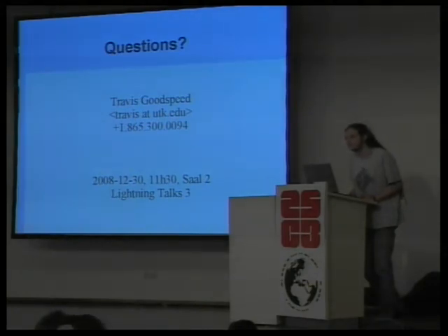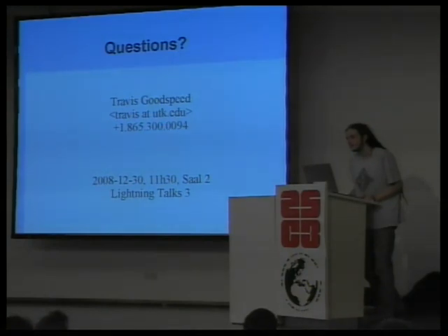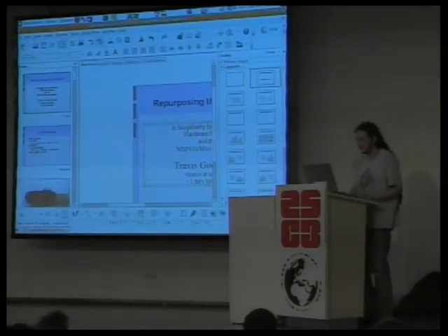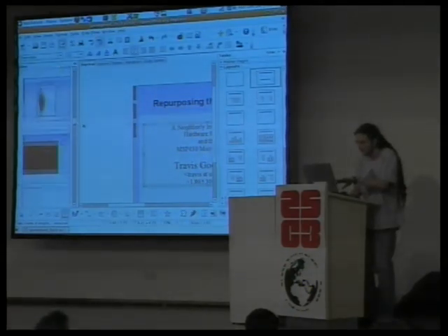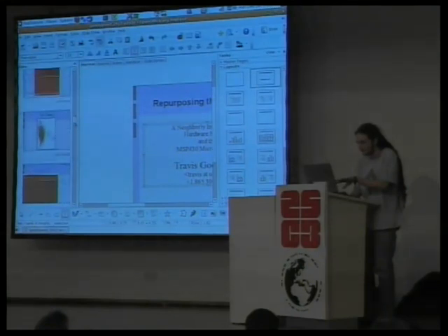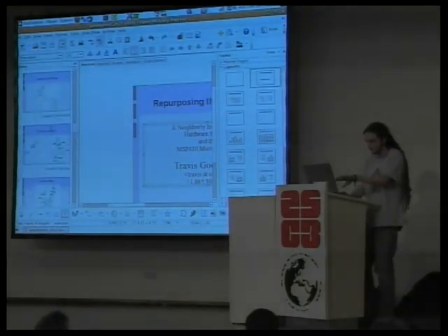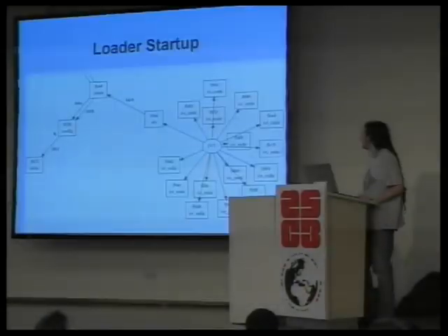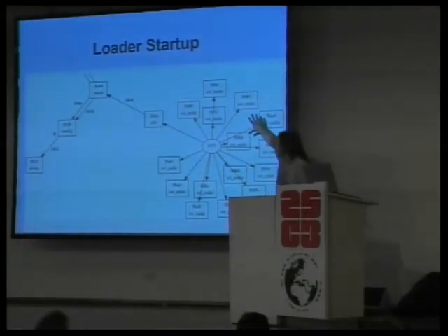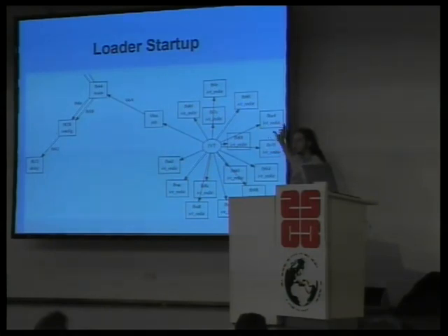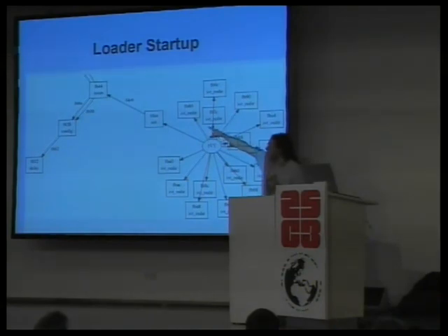Shouldn't there be an entry point from the interrupt vector table, from the init function, also to the main loop? Yes, I'll load that up. Here we go. This one. So you have the interrupt vector table here. And then all of these orphan functions that are just squares that don't go anywhere, those are proxied to the lower firmware image. The only exception is init, which then calls main directly.